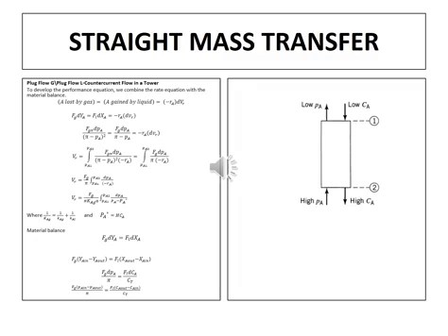The important thing to note here is that we should always arrange Y in minus Y out so that it is positive, and the same thing with the X's. It should be X out minus X in so that it is positive. This is for a countercurrent system. If this was co-current, you should still make sure that the change in Y is positive, and the change in X is also positive.